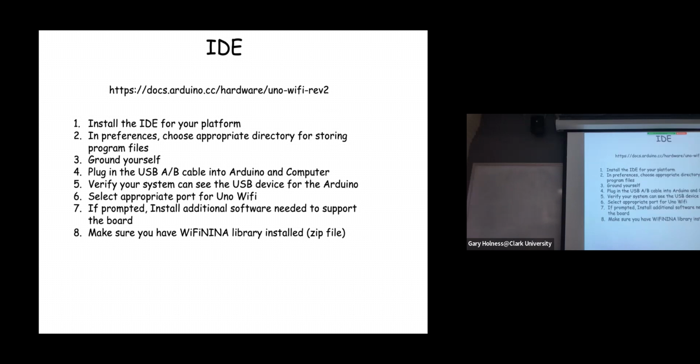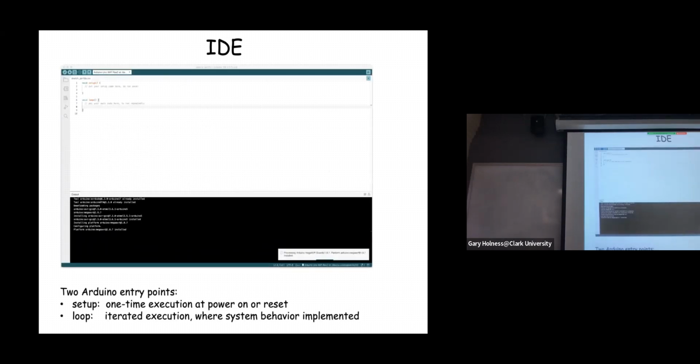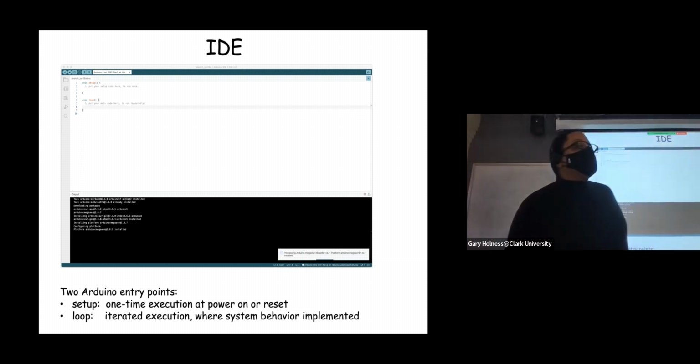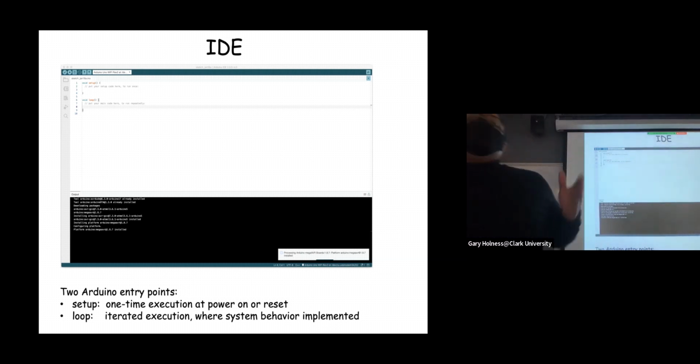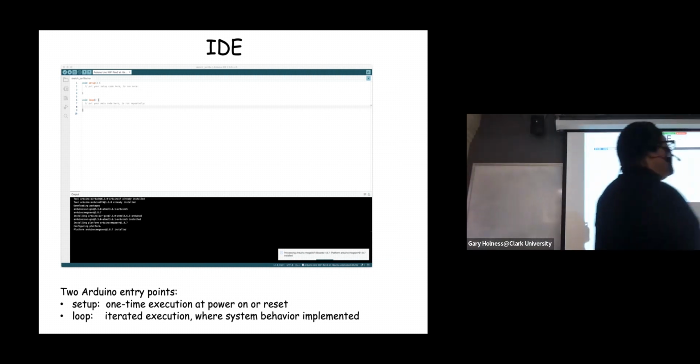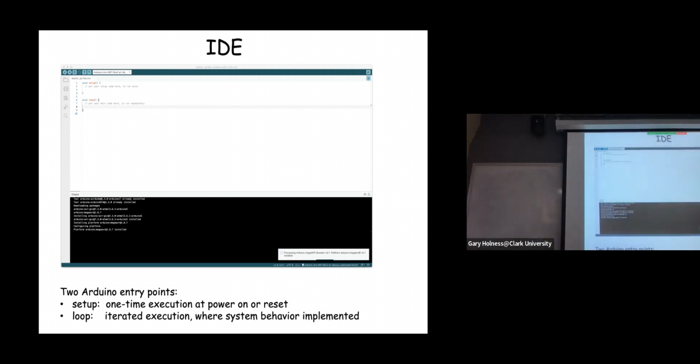Any questions? No. So that's what lies ahead at noon session. This is what the IDE looks like when you first start up and create a new program. The basic program has 2 entry points. Now, this is the sketch language, C++. It's block structured like Python, but instead of using indentation to define your blocks of behavior for your program, you have the open and close curly brace. So it's exactly like Java in that regard.